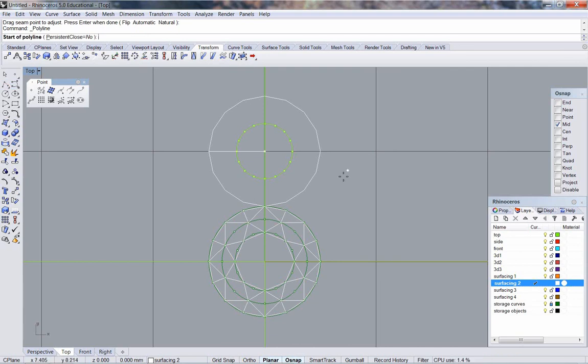And we'll only draw one. We need end snap and point snap. When you're going to draw, it's always good to think to yourself, which constraints do I need? Do I need object snaps? Do I need grid snaps? Do I need orthographic, holding down the shift key snap? Do I need to type in a dimension snap? Do I need to type in a degree constraint? Think ahead as to what kind of constraints you want to apply to your cursor as you're drawing.